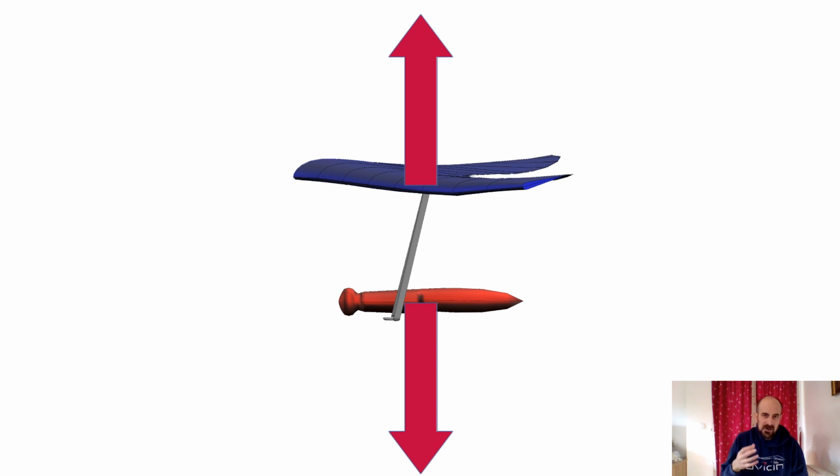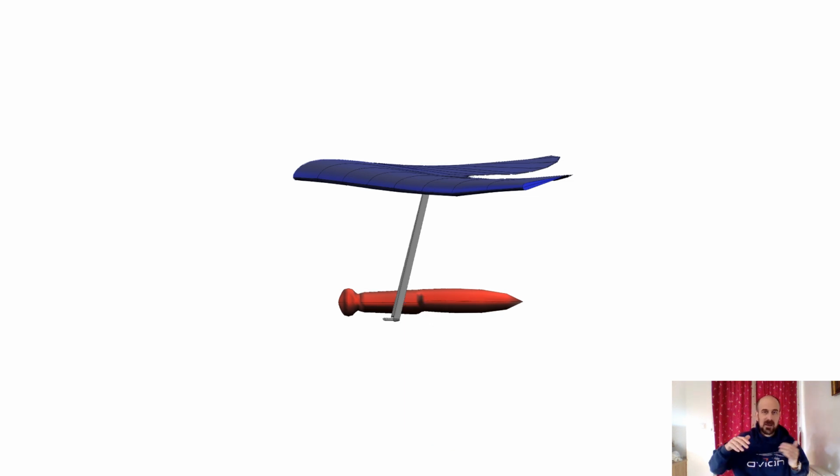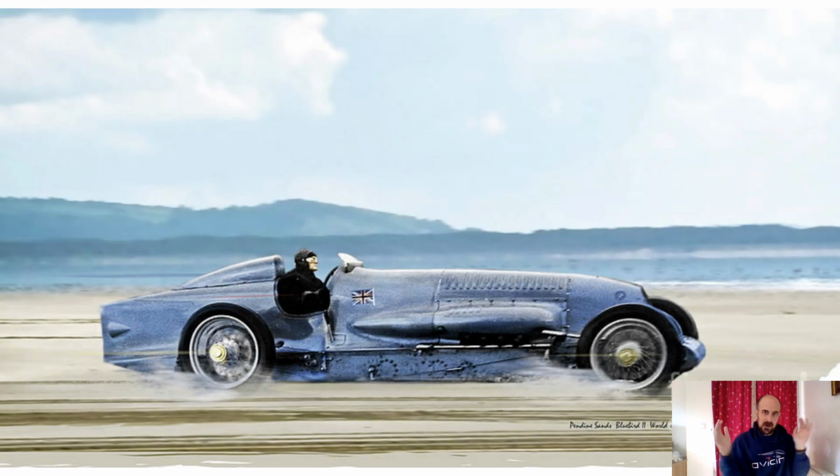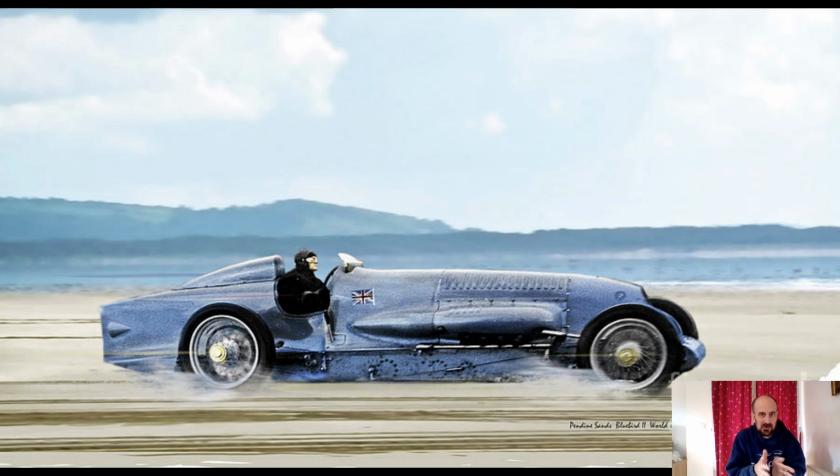Now, where that kind of thinking can lead is that we concentrate very heavily on the drag side of the equation, and we don't think enough about the lift side of the equation. A lot of hang glider development over the years has been to do with streamlining and reducing the obvious sources of drag. So it's treated a little bit like trying to make a car go faster, where it's kind of obvious what you need to do to reduce the drag.